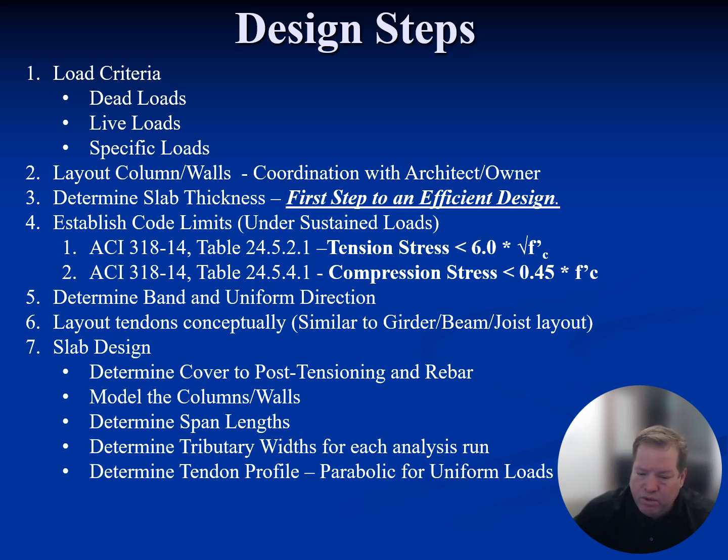We typically use parabolic profiles in two-way slabs because parabolic profiles work well to resist uniform loads, which typically is what we're supporting or resisting in two-way flat plates. Again, parking, hotels, apartments, stuff like that. You're always dealing with 20 pounds a square foot dead, 50 pounds a square foot live or something like that. You apply the loading, do the design, and then be accurate.